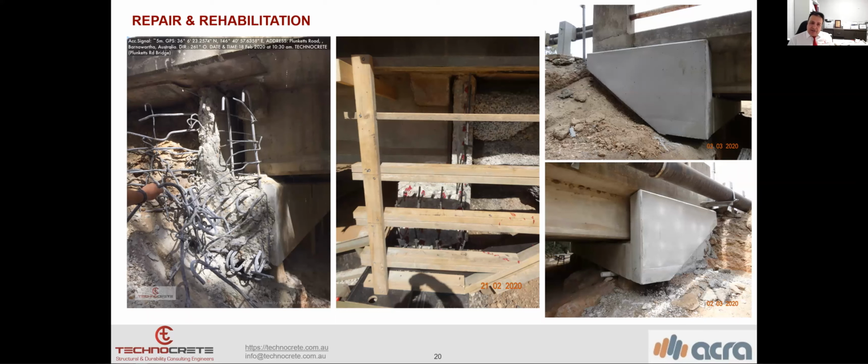But the other defects depend on the quality of the concrete. I mean, we need a little bit more information in order to judge or interpret the tests which we have to do and the deterioration mechanism involved with the structure. With the soft water attack, we have to investigate the corrosion and the concrete quality. These are the types of non-destructive investigation which we have to do. We need more information.